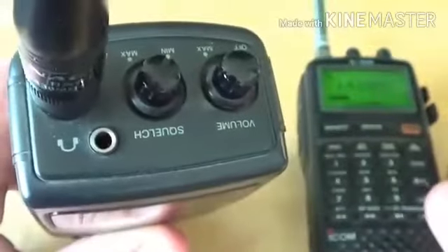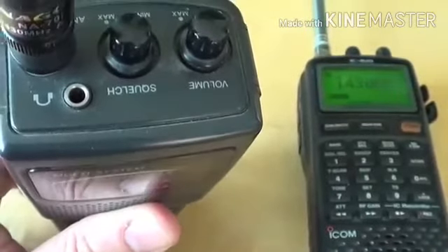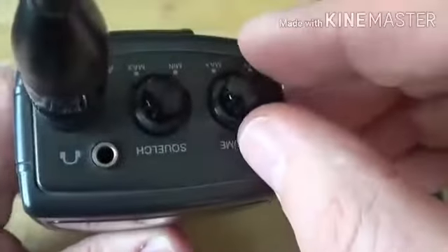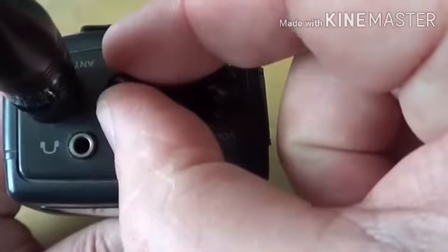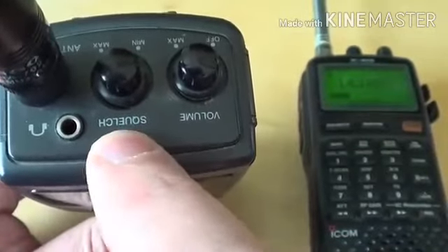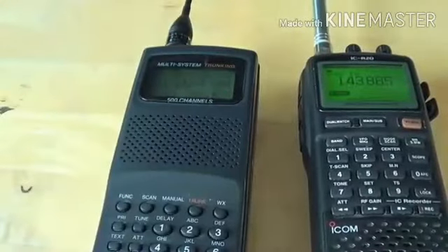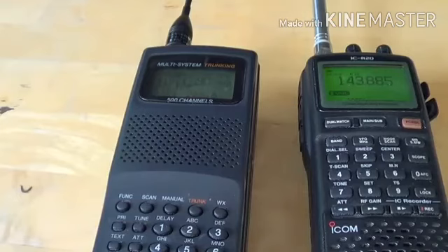Technically, you want to set the squelch to the lowest setting that you can put it at, where the static stops. So for example, I want to set the squelch here. I'll just start turning it, and as soon as the static stops, I'm going to stop turning the squelch button. The reason why you can't put the squelch too high is the higher you put the squelch, the stronger the signal needs to be in order to actually be heard on the radio. So if you put your squelch level very high, you won't hear a lot of signals.